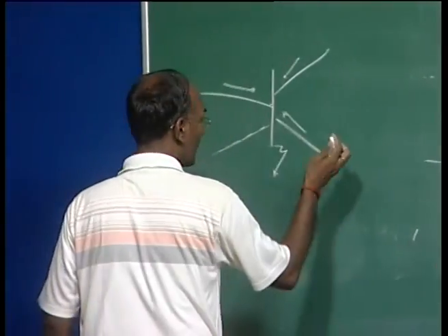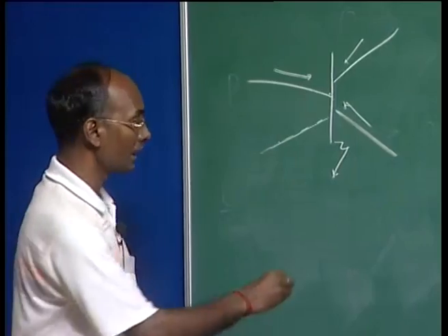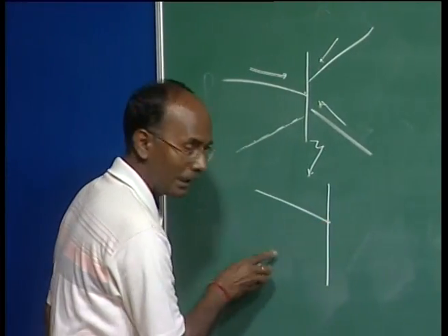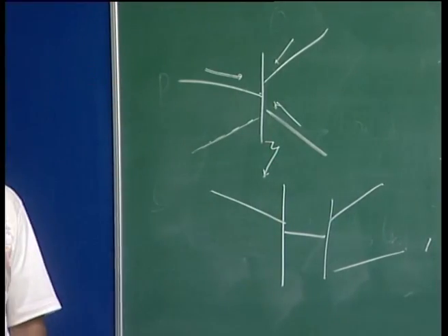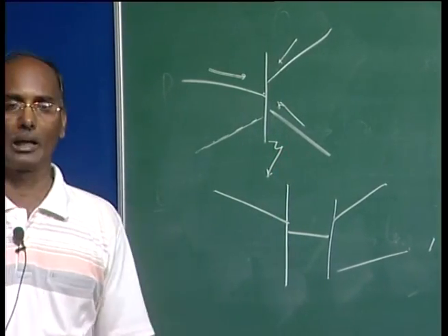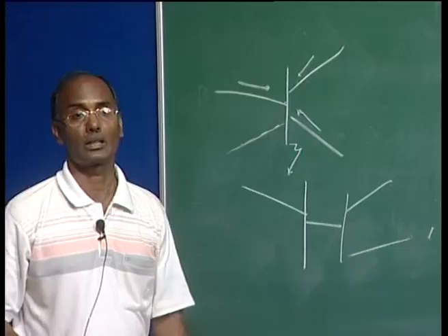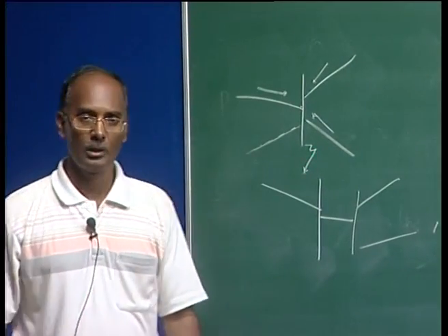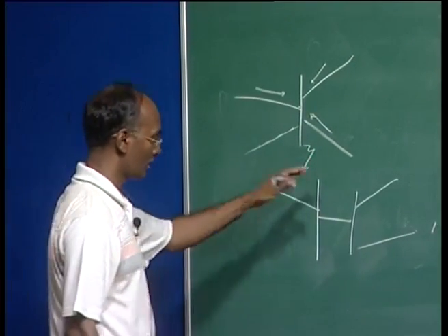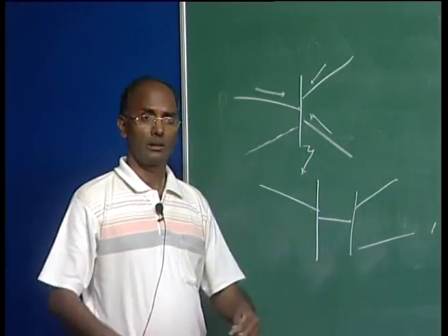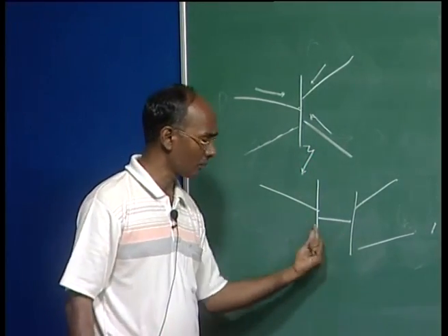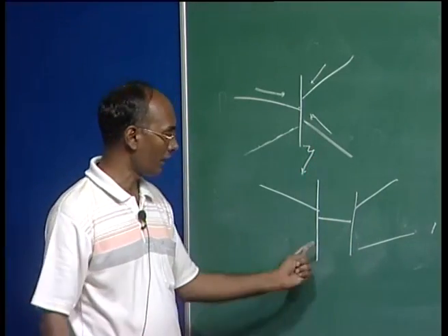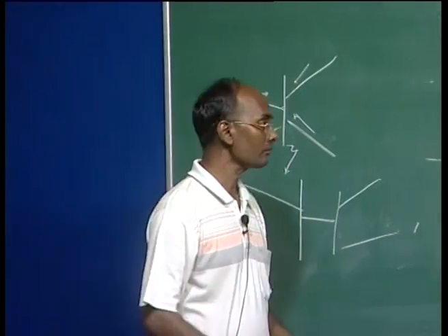What we do is go for bus splitting. Bus splitting means a few lines are connected here, and then another few lines are connected there. That reduces the fault level, and thereby we can save the cost of circuit breaker replacement. In our UP system, at several locations it is planned, when we expand our network, to have bus splitting, with two buses at the same position, so that the fault level can be reduced.